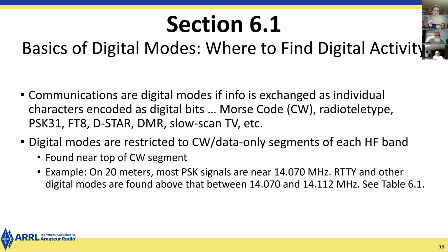And you'll see in the chart in your manual that the digital modes are usually on frequencies near the high end of the CW segment, and they generally don't interfere with each other. People are generally pretty considerate of others here, so that, for instance, you don't hear a PSK or an RTTY, radio teletype, signal where FT8 is normally used on those frequencies.